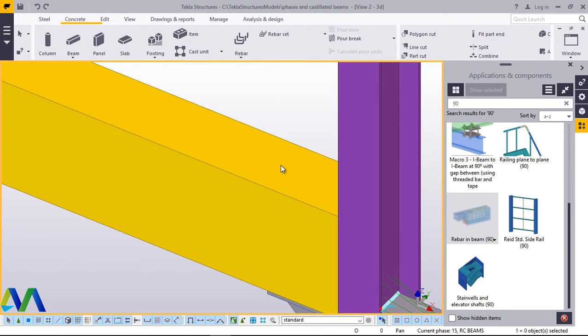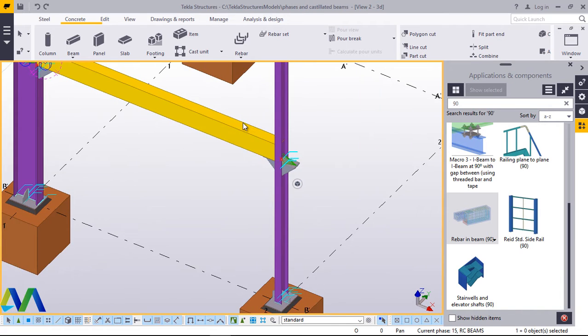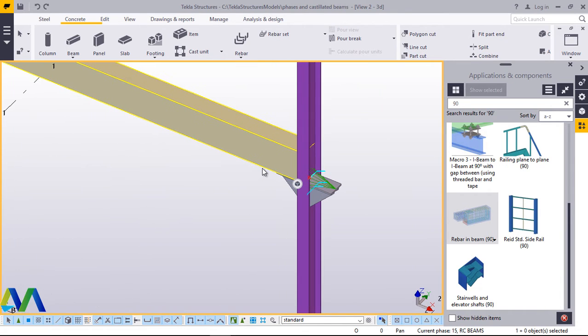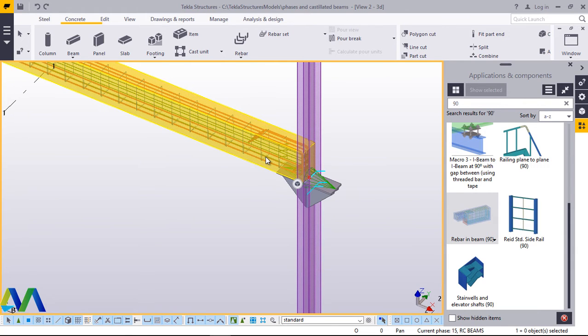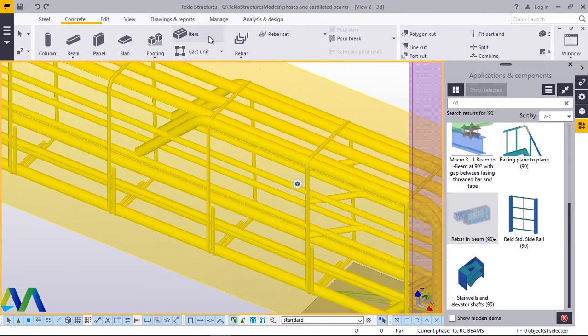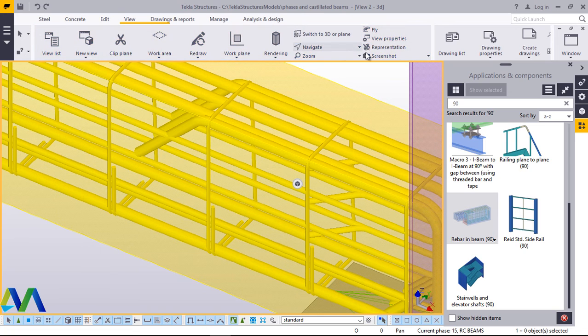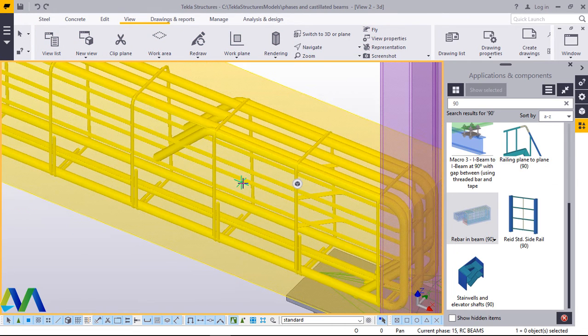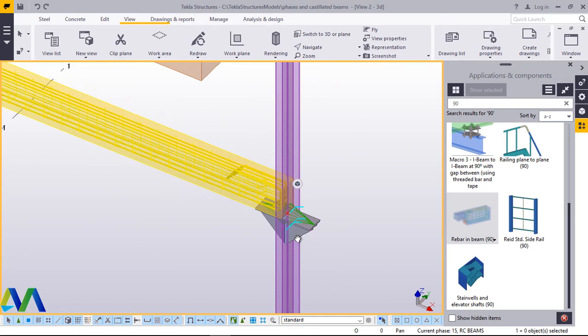Remember, once you've made your previous settings in setting how the rebars will be located on the beam, it will pick the same settings and apply into another beam, but it will be able to adjust the spacing of the rebars, the space in between the rebars. I'll press Ctrl 2 for us to be able to see inside the beam. This is inside the beam that are on the side of the gable.